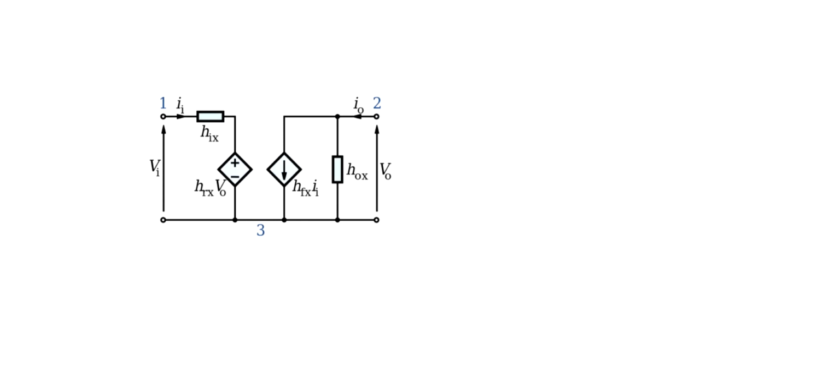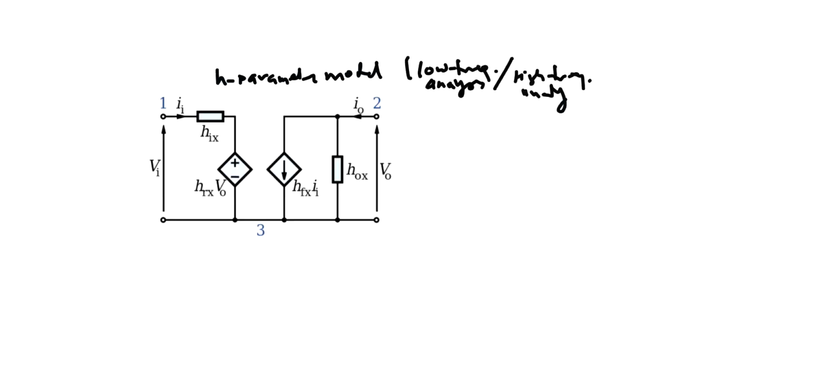Generally, we use the H parameter model for low frequency analysis and also high frequency analysis. For high frequency, you need to incorporate the capacitances into the model.